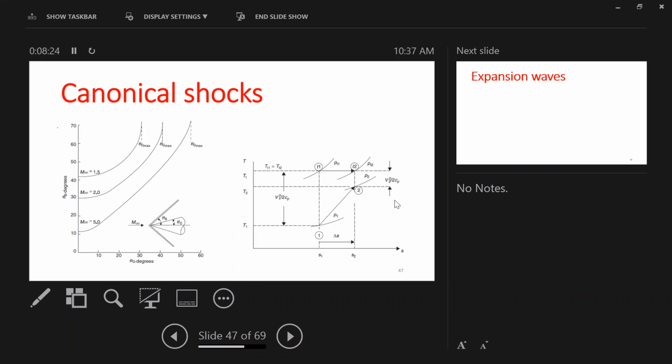The idea was for thetas higher than this, you are not going to have an oblique shock wave. You're going to have a separated shock wave. So essentially, your shock wave is going to look like this, and it's going to happen sooner. But when you are dealing with a cone, you are dealing with a three-dimensional case, so your shock wave is completely separated. It is going to look something like this, right?